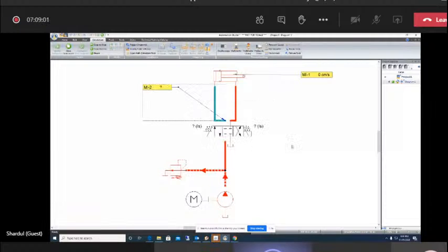So these measuring instruments are really very useful for watching the dynamic simulation properties change with respect to different parameters. For example, if I now see I have a pressure of 120 bars here. Now, if I increase the pressure of the relief valve here, you will see that the pressure will start to increase. So this is how dynamically the properties are changed here.